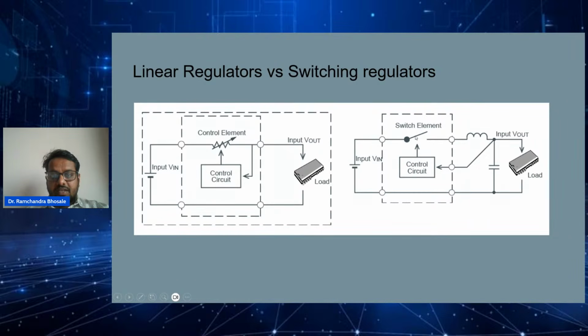So what is the advantage in this case? In this case, most of the voltage is getting dropped across this resistor, so the efficiency will be less. But here, as you are passing energy for some time and then completely opening it up, it will not behave like a true resistor. So here you are getting better efficiency.